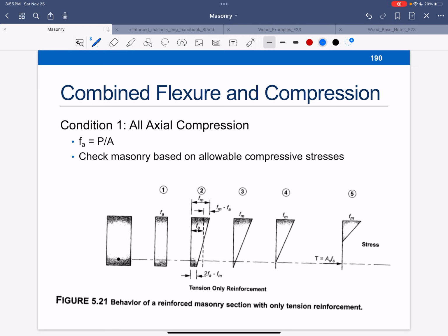So there's going to be some type of thing. If I was doing concrete, I'd have my P and my moment, like this, and I'd end up with the case of pure axial. Okay, so no moment at all. And then I'd have some other cases along here. We have balanced, we have another case along here, and then we typically have where it kicks back in this direction, and I come up with an interaction diagram. So I'm going to do kind of the same thing and just show you the points that you'd have for the masonry. It's a similar thing.